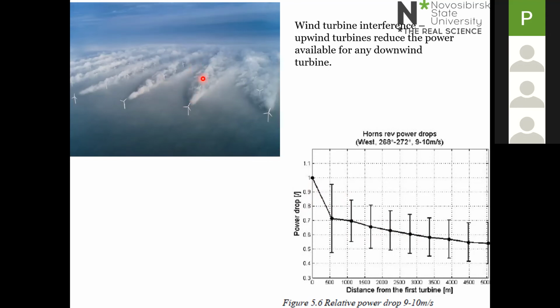And it also shows you the importance of knowing the wind direction, because these interference effects are primarily caused by the wind direction aligning with directions of rows of the turbines. So offshore wind farms don't use a layout like this, or alternatively, one would hope that the wind blowing in that direction is a very rare occurrence for this particular wind farm. Like I said, it's impossible to prevent this from happening. You just want to design or lay out your wind farm so that you minimize the effect of one turbine interfering with another.